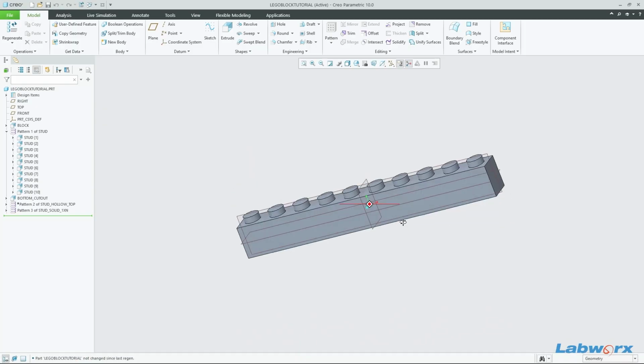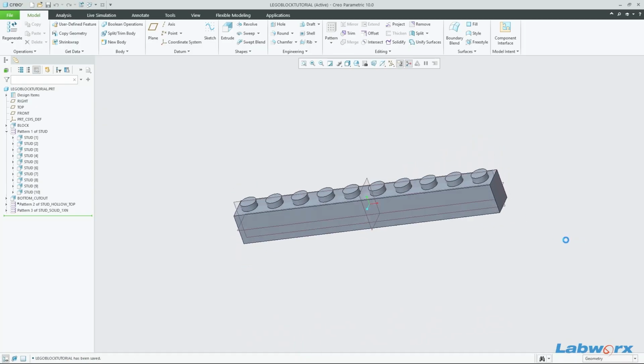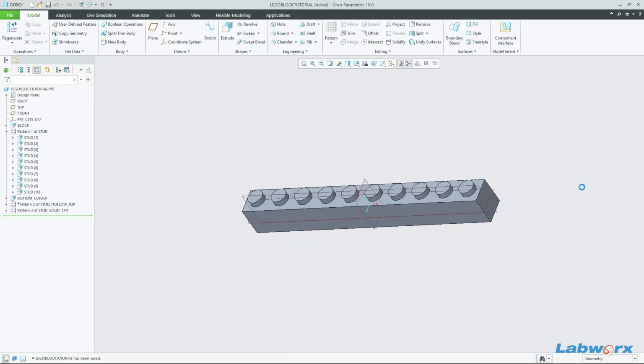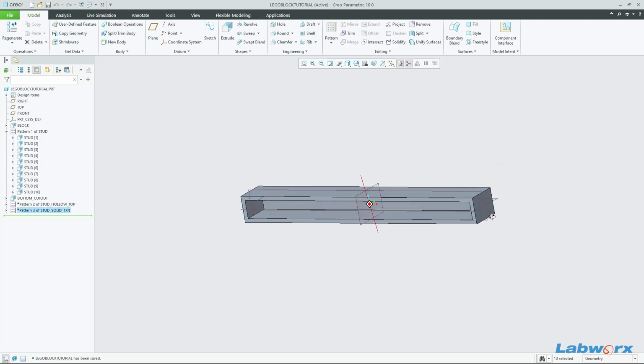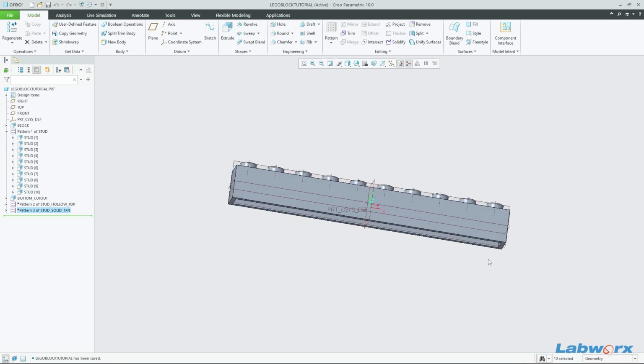So now that we've got the 1x1 parts completed, which is working really well, we need to suppress our pattern over here, switch that off now, and we're going to start working on the other condition, which is n by n, where n studs is above 1.